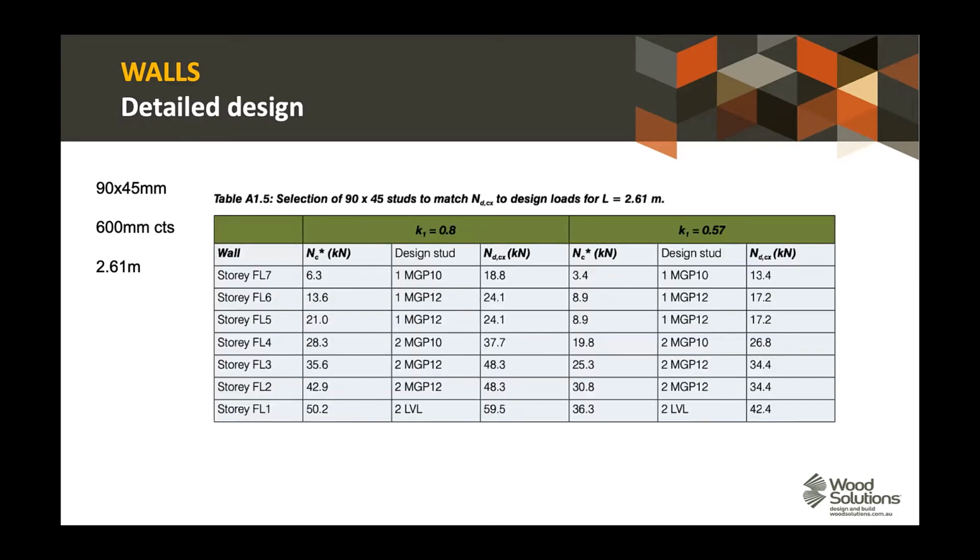So looking at the walls again, what we've done is we've set out for the different stories what stud design you would look to as a minimum for this seven-storey structure to get the performance that we need, based on all the checks being conducted to 1720. So for stud design, we haven't had to look outside of Australian standards for either the models or the design steps that we need there.